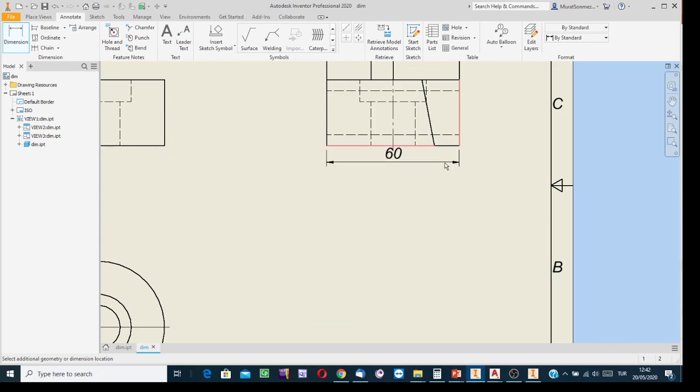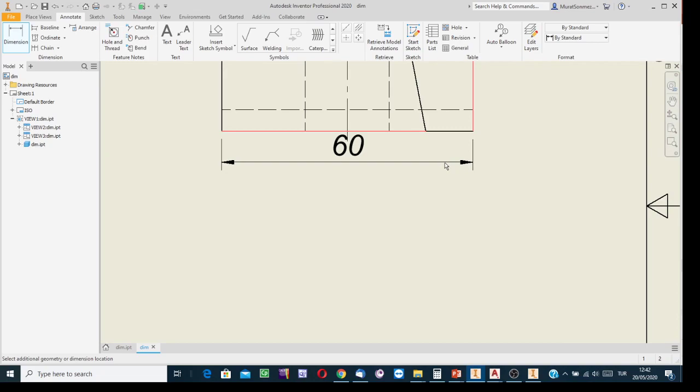Well, in Inventor, how can you be sure that the dimensioning line is 10 millimeters away? If it is not 10 millimeters away, then in the simulation you see the extension and dimension lines as continuous lines. But you see, slowly moving the cursor together with the simulation, now the lines are in dotted form.